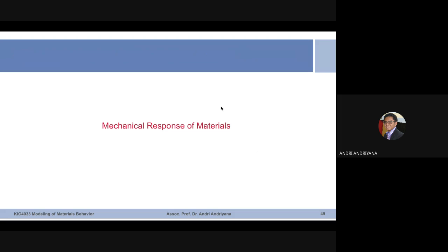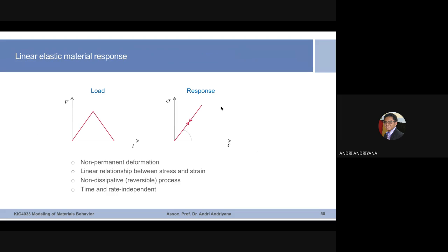It is similar to the example that we have seen before, where we impose loading and unloading. We impose load and we remove load, and then from that you will see that different materials could show different stress strain responses. Okay, so the first one here is that I'm focusing on imposing the load during the tensile test in the form of force control or stress control.